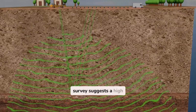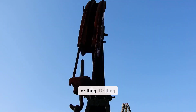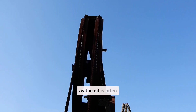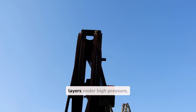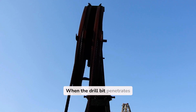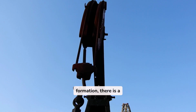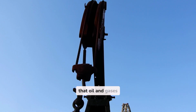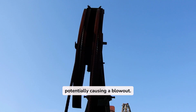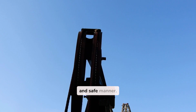Once the seismic survey suggests a high probability of oil, the next step is to confirm it through actual drilling. Drilling for oil is far more complex than drilling for water, as the oil is often trapped within porous rock layers under high pressure, sometimes accompanied by gases. When the drill bit penetrates the strong cap rock and enters the oil-bearing formation, there is a significant risk that oil and gases may surge upwards under high pressure, potentially causing a blowout. To prevent such incidents, the drilling process is conducted in a highly controlled and safe manner.